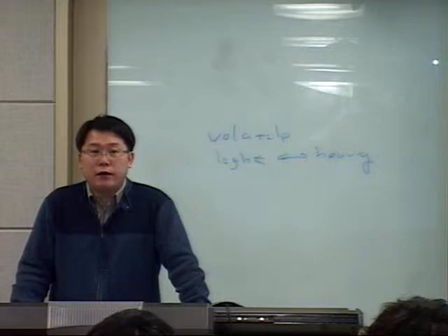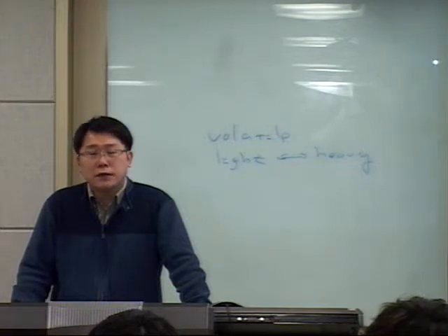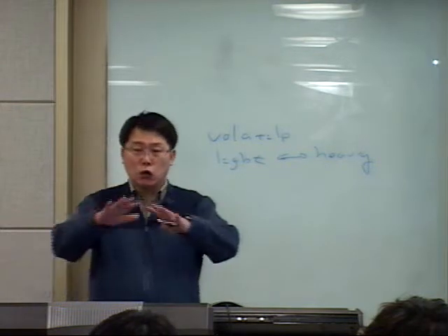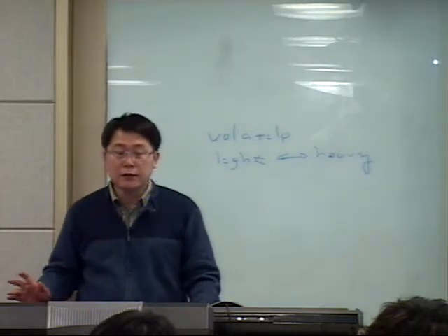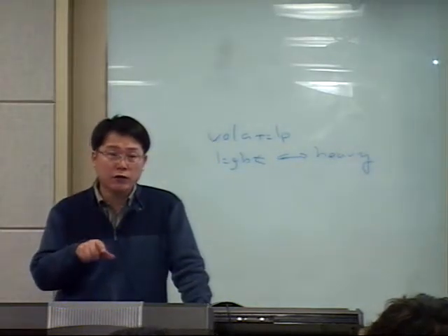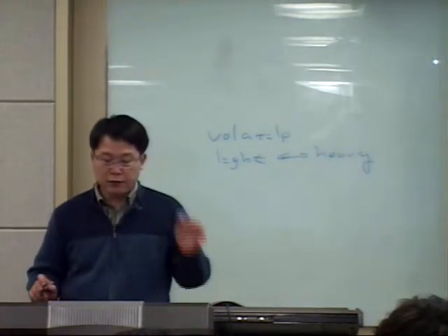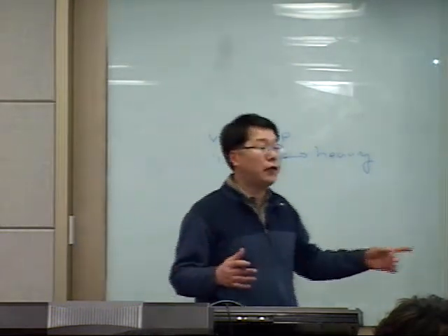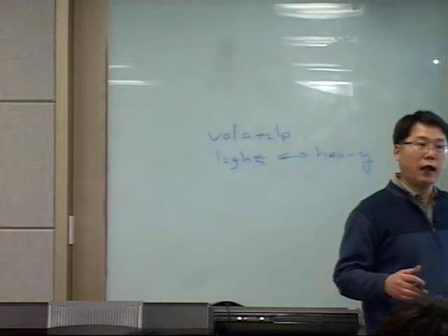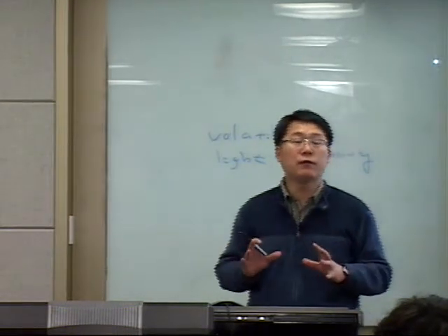So the ship owner of the LNG carrier wanted to check what happens if we just close the cargo containment system. So this is the question. In this case, we have heat ingress from outside, and we cannot remove BOG from the cargo tank.